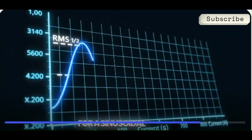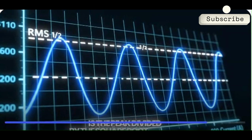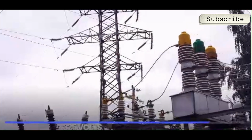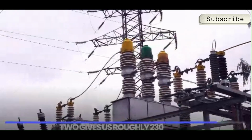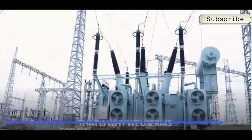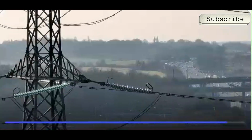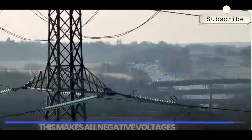For a sinusoidal wave, the math dictates that the RMS is the peak divided by the square root of 2. 325 volts peak divided by root 2 gives us roughly 230 volts. That is why we use RMS for all AC power calculations. Since power is proportional to V squared, this makes all negative voltages positive.